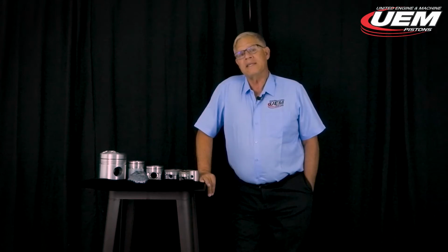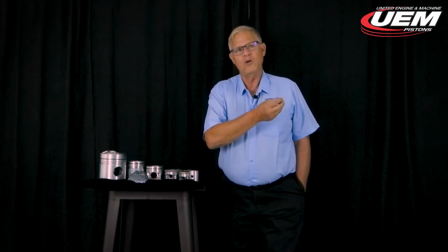Now, the reason this is important to you as an engine builder is you can pick these characteristics that you want to apply to your motor. If you feel thermal properties and low thermal expansion is more important, then you'll want to move towards the hyper side of the selection of alloys. If ductility is your characteristic, then without a doubt 2618, but then you lose these thermal properties, they just aren't as good. And so again, it becomes a choice that you have.